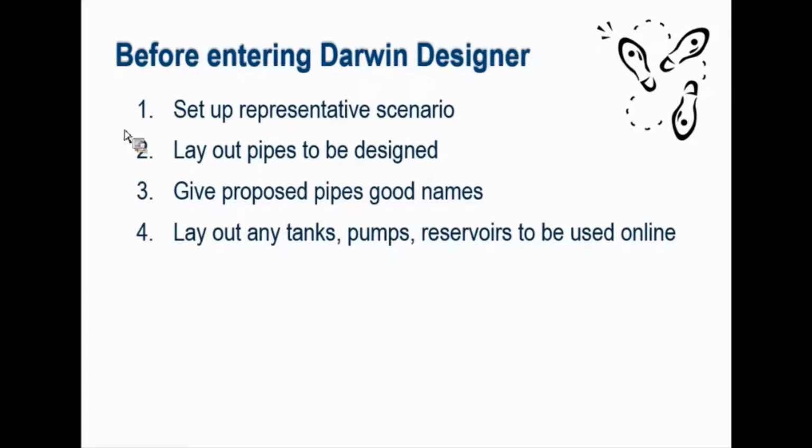And also something to consider, when you're laying out the pipes to be designed in step 2, what that really means is you are going to select the path, the potential locations that pipes are going to be. And this is another area where a computer could go design a whole entire system, right? But it could be drawing a pipeline right through a building, right through a lake or a pond or something, or right through a sewer main. You, the modeler, would know about these things by seeing the overlay of the data and knowing that those are important elements that you can't put a pipeline through.